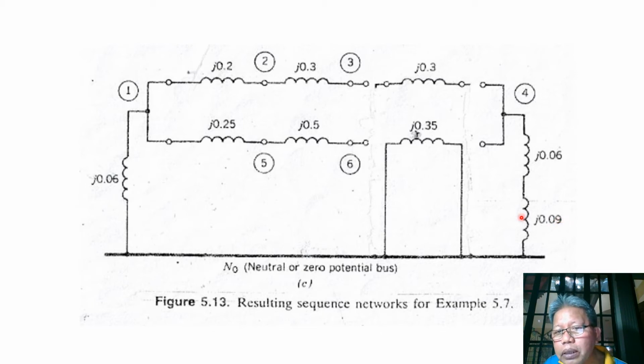Now, remembering the grounding reactance that we have of 0.03, since three zero sequence currents IA0, IB0, and IC0 flow through this grounding reactance, we multiply the original value of 0.03 by 3, so it becomes 0.09. Now down here between bus 1 and bus 5, we have transformer 3, which is YY connected and